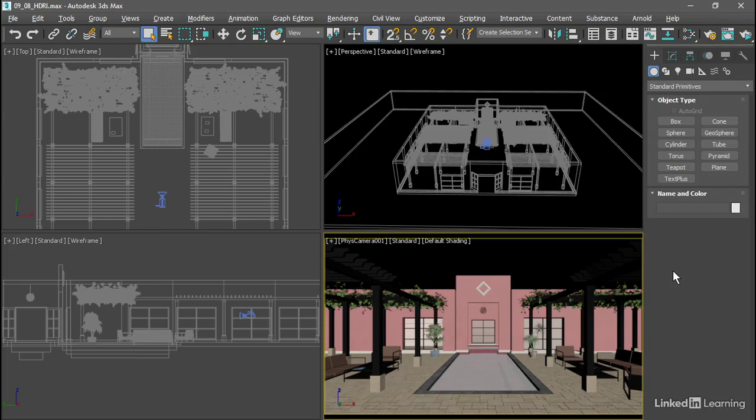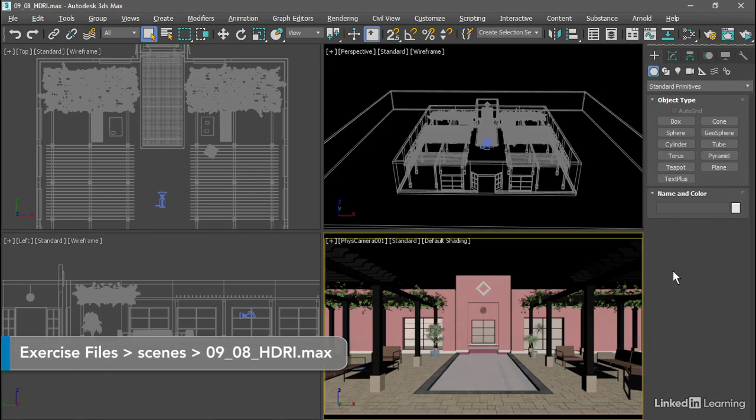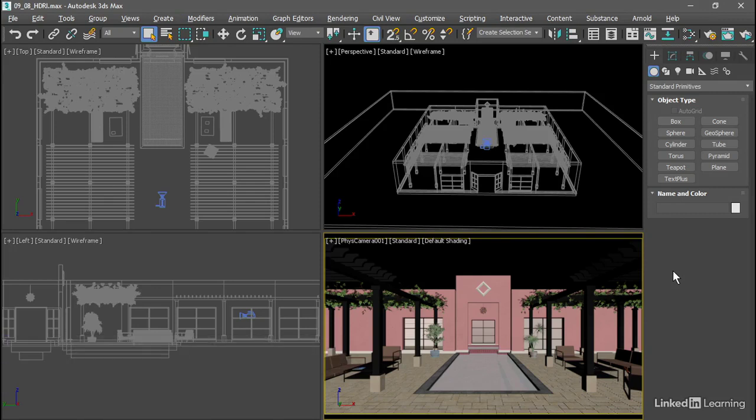The next level up in environment lighting is to use a high dynamic range image panorama, also known as image-based lighting. So we can apply an image to our background and environment. It does need to be a high dynamic range image to work well, meaning that the pixel values are based upon physical intensities. So if you just drop an ordinary image into the environment slot, you're not going to get good image-based lighting. It does need to be a special high dynamic range image.